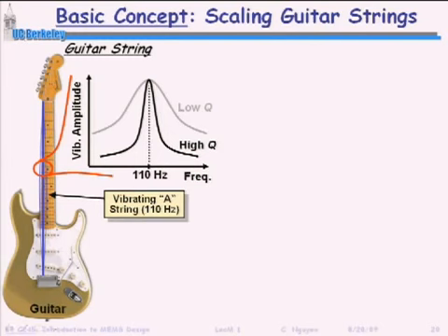And that's what we're transmitting electromagnetically. That's what's going through the airwaves. But as soon as that signal hits your antenna, it needs to be processed. It needs to be filtered. Because we're transmitting information at all frequencies from 100 megahertz to 3 gigahertz and beyond, actually. If your antenna is picking up all those frequencies, how are you going to figure out which one belongs to your conversation as opposed to someone else's? You've got to pick one frequency, and that's what this is doing.